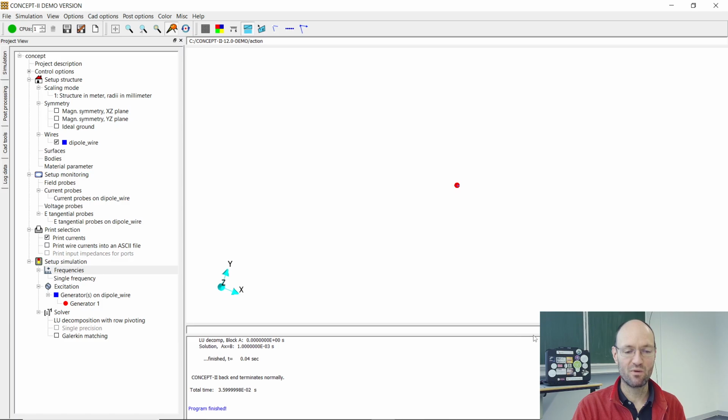If I look on the wire from the top, why should something depend on the angle around the wire? So what we could do now is to make this model more complex. If we think about electromagnetic compatibility and radiated emission testing, then typically our equipment under test will be much more complex. There will be not one straight wire that radiates, but